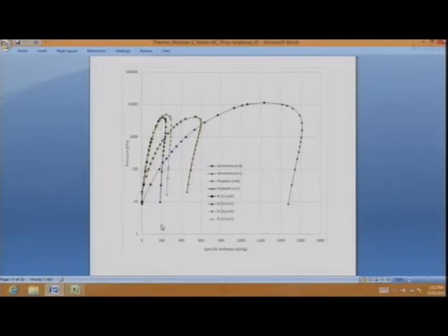The other thing that this sort of a picture tells us is what are the substances that have somewhat similar properties. And this issue came up 20 years back when R12 as a refrigerant was banned because of ozone layer depletion. And the immediate question people started asking was what is the material that I can put in my refrigerator and air conditioners. So people started looking at these properties and said, let's see what all materials we have.